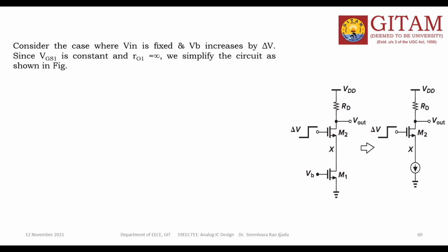The important parameter here is finding the voltage Vx. Because there are two transistors connected in cascoding mode, and each individual transistor must be kept in saturation, the potential of its gate-drain must be much greater than the overdrive potential of the respective transistor. Based on that, I'm going to calculate the Vx value.